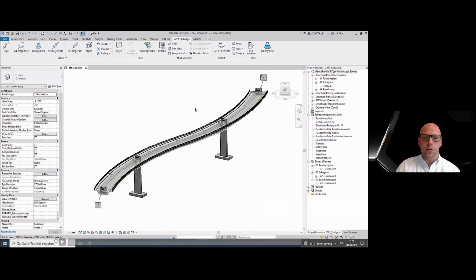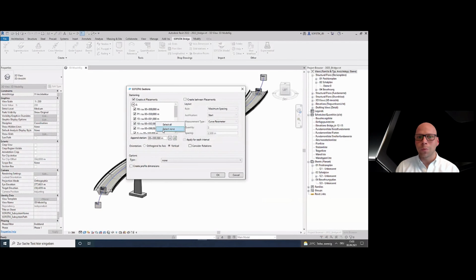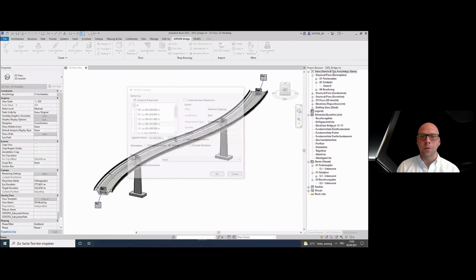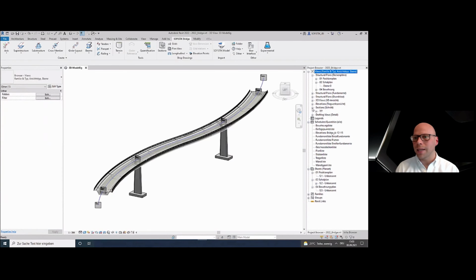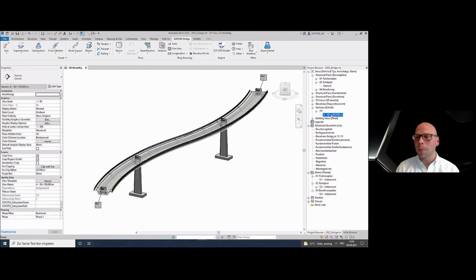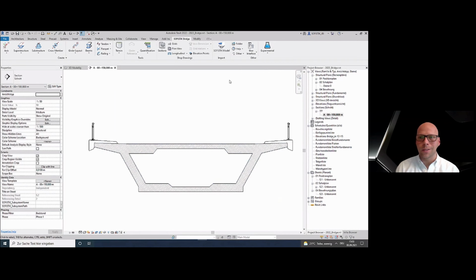The section views is the command that you know from previous webinars or also AU classes, but right now we have the possibility to select the station manually or graphically in the plan, or simply type in any given station that you want. When we open the section, we can see that, of course, it's empty.